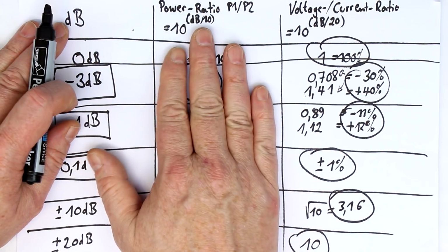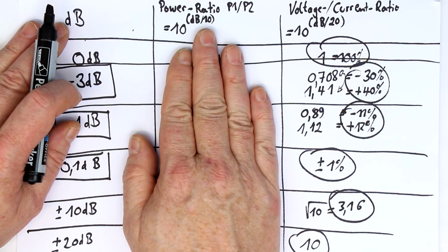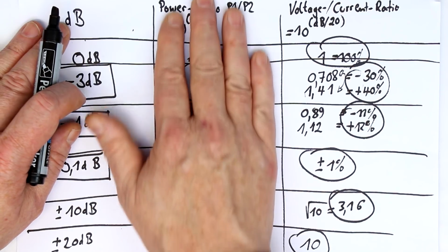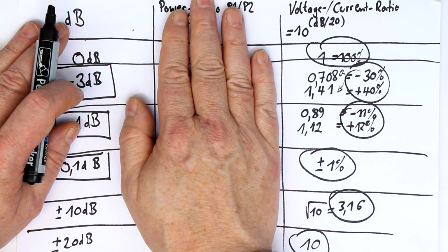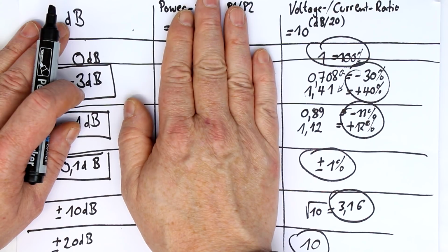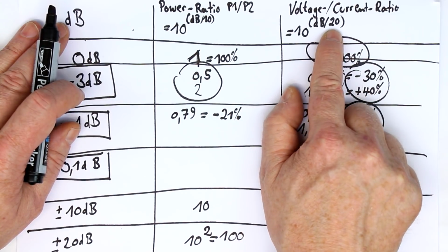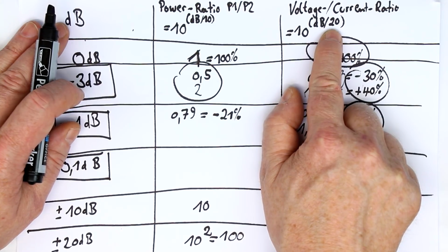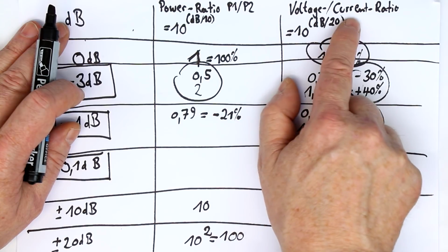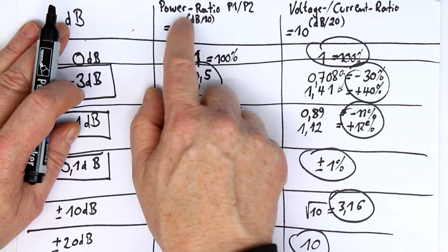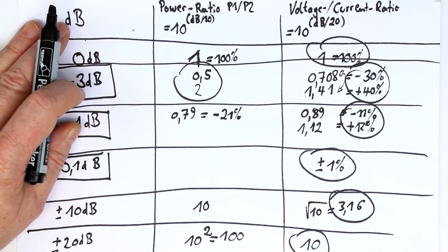And because you usually don't have to deal with the power ratios, simply because you don't measure them, you can most often forget them. But now you know where this 20 is coming from. It's the combination of the decibel in bell, and because voltage and current are squared when you want to get to power.